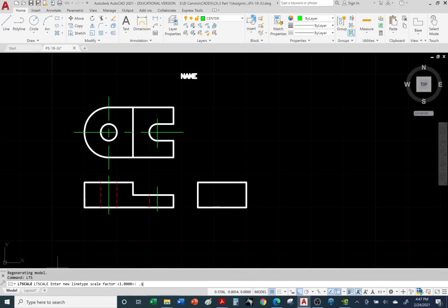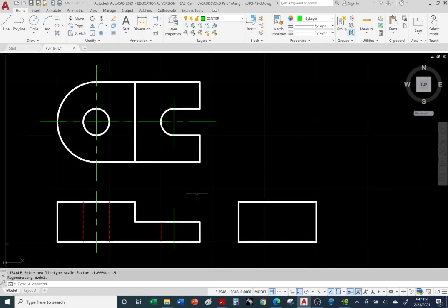Okay, 3, 2, 1, don't blink. I enter, and hey, that looks a lot cleaner. Okay, so don't do LTS towards the very end. Once you complete your drawing, then play around with the LTS. If I don't see the dashes when I grade your work, it's okay. I'm not going to take points off. As long as the red hidden line is in the right layer, I'm okay with it. I don't want you to get frustrated trying to show the gaps between the dashes.